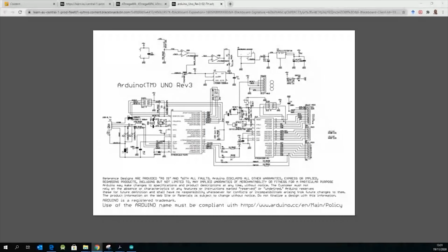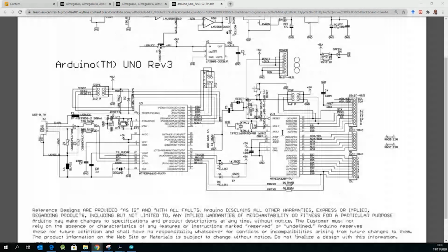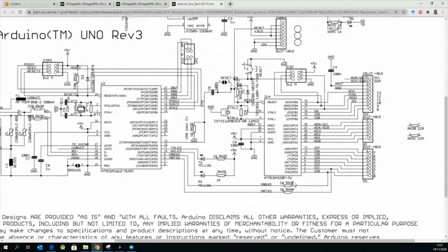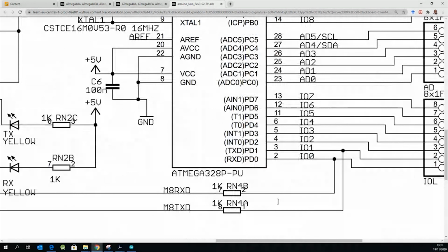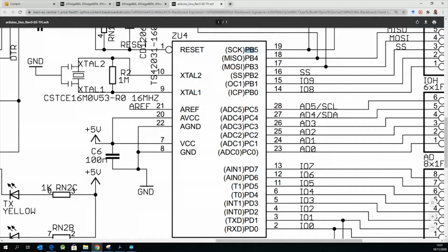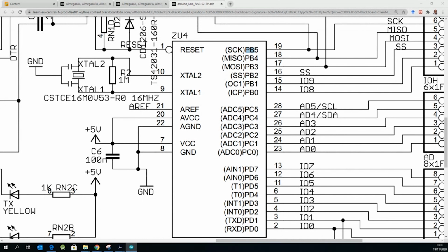SRAM. So first of all, if we have a look at the Uno R3 development board, you've got the ATmega328P chip. That is the one that we are interested in. And the ATmega328P, you've got the 3 ports on there. So you've got port D, port C, and then you've got port B on there for you to use. Each of them is 8 bits.